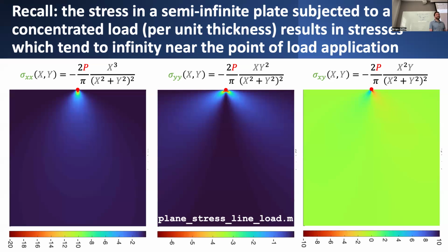And you'll see various other solutions, including some very important solutions, like in the case of fracture mechanics, where you want to know the distribution of stresses in the local vicinity of some crack tip. There too, the solution ends up being infinite, or you have infinite stresses in the local vicinity of a crack tip. But that's simply not possible. Even though it's very useful to have, ultimately it's still unphysical because it hinges on this assumption of linear elastic constitutive behavior.